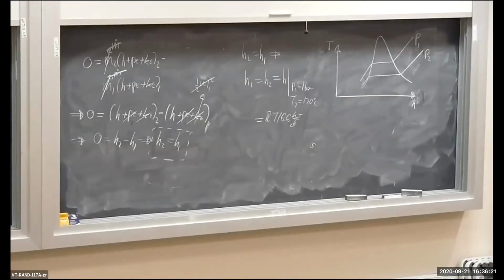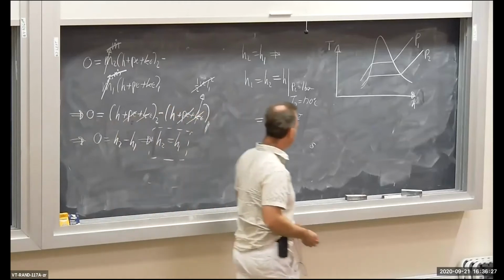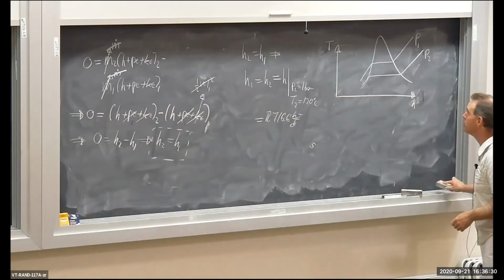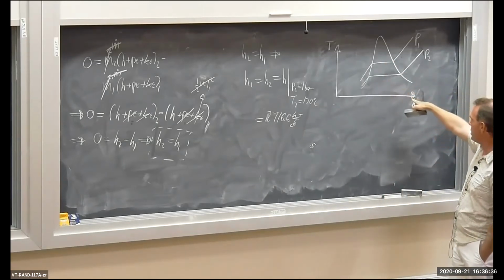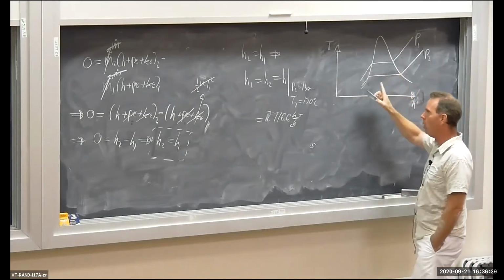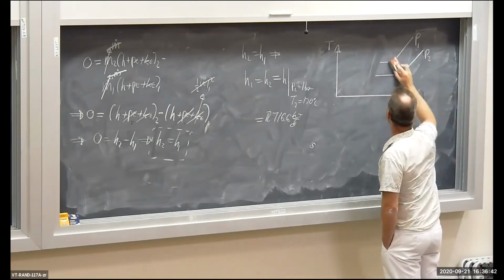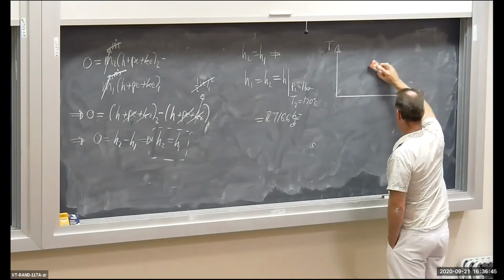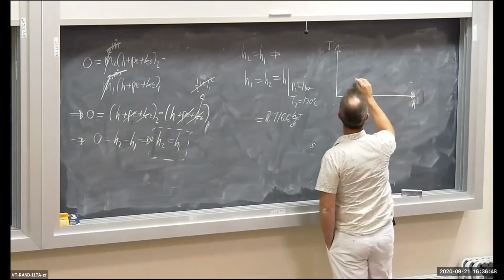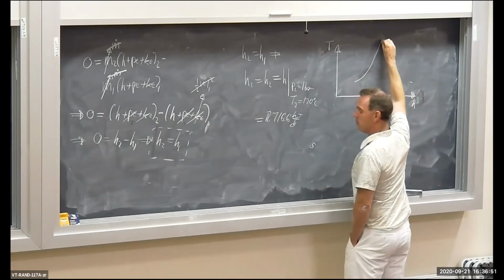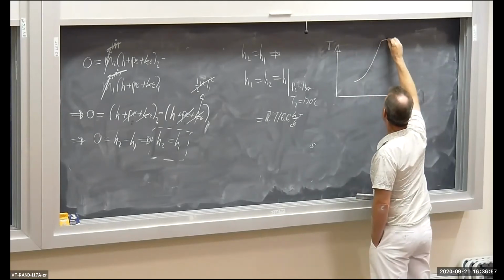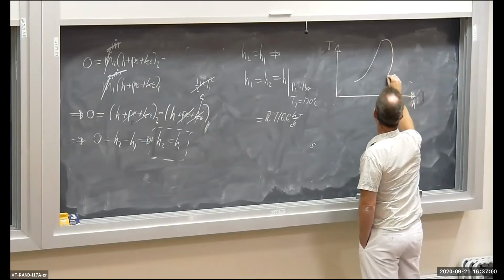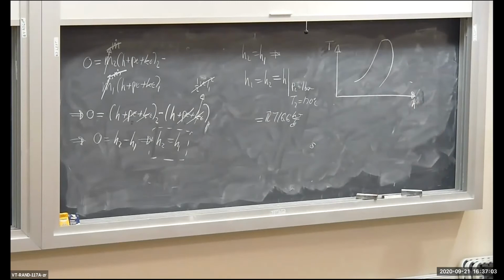Okay, so let's continue on here. One little thing I want to clarify. I usually don't use the TH diagram, so I think I might have misspoken a little earlier. There is a saturation dome on the TH plot, but it's qualitatively similar, not exactly the same. The TH plot looks like the TV plot on the saturated liquid side, but on the saturated vapor side, it folds over on itself, or curves over and becomes concave.